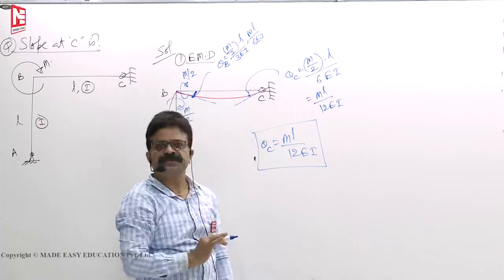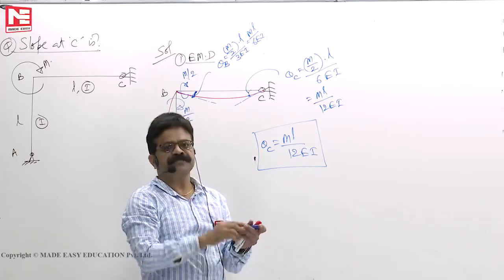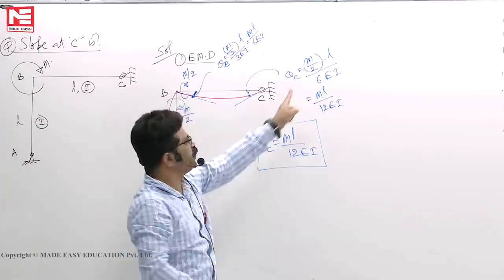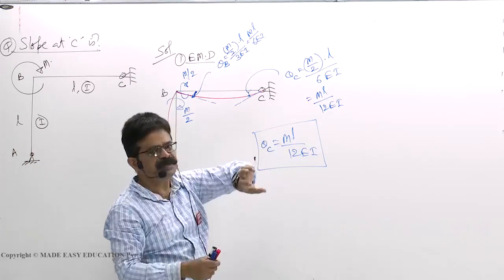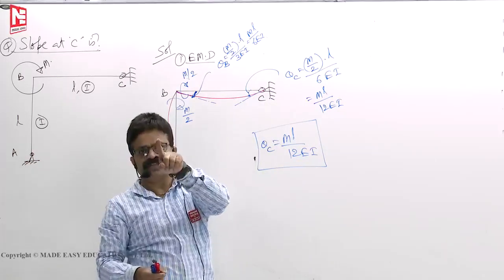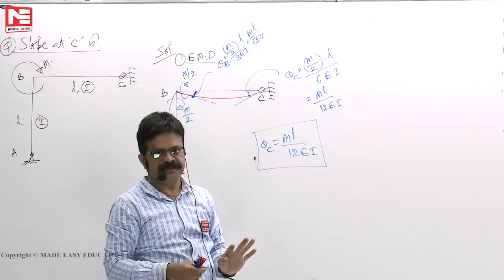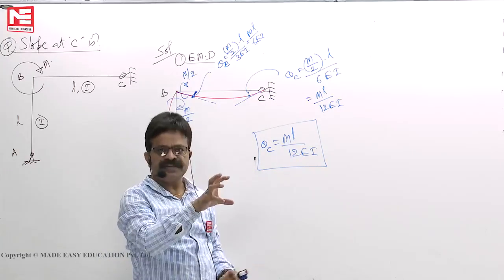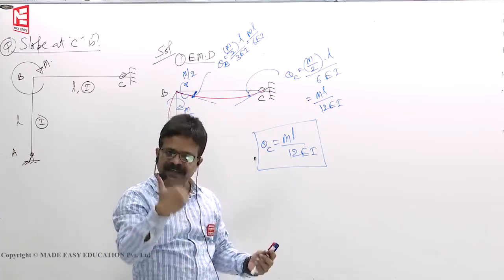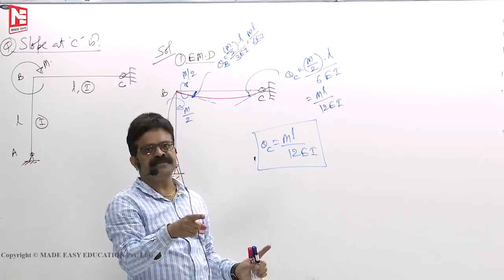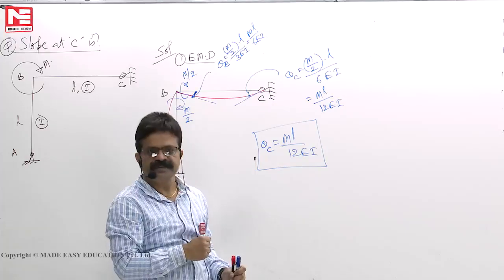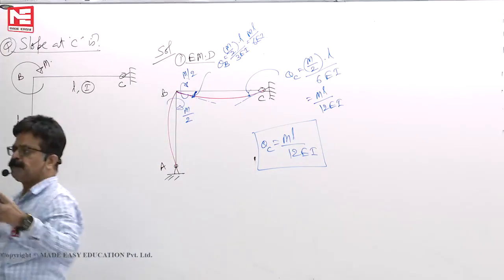This is a 2 marks question, so you have to be careful. If you know the deflection profile and the end condition, hinge is there, and here you are applying a moment. It is like a simply supported beam subjected to moment M. A rigid joint is there with M by 2 moment, and now I can read that as a simply supported one applying some moment M. The behavior is the same.